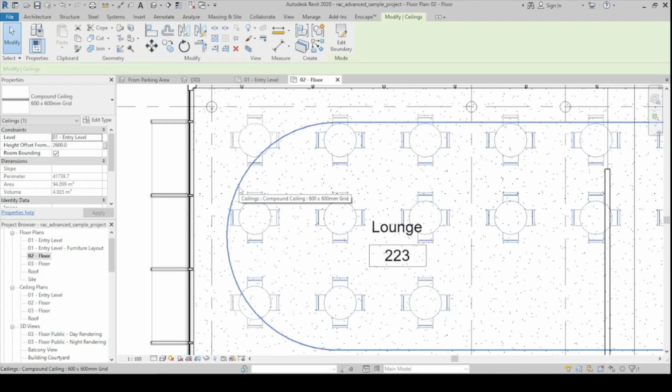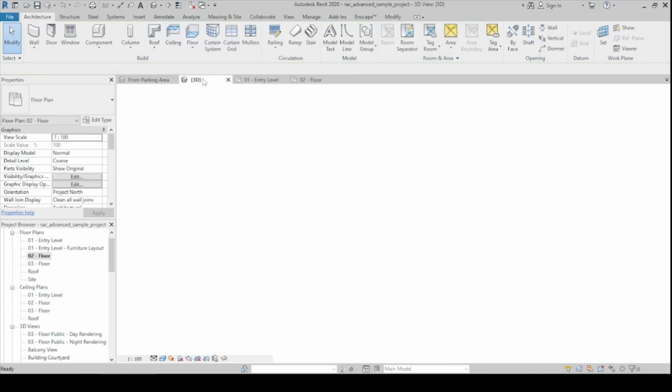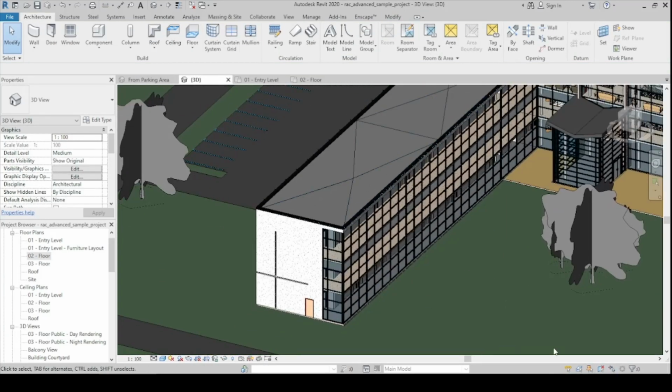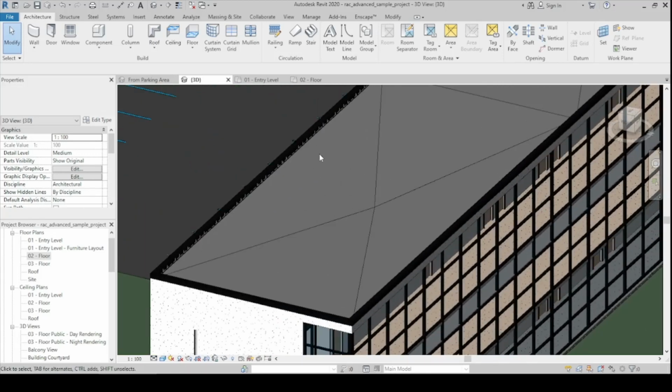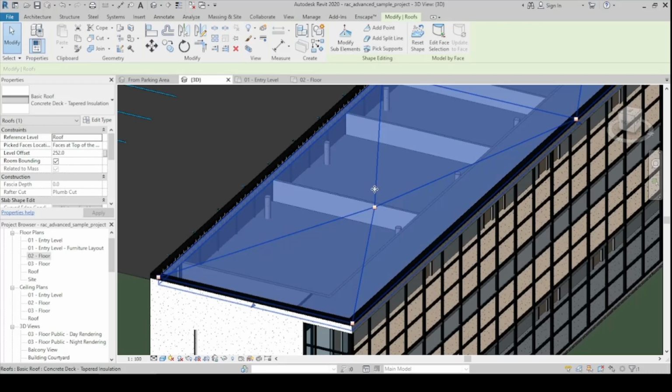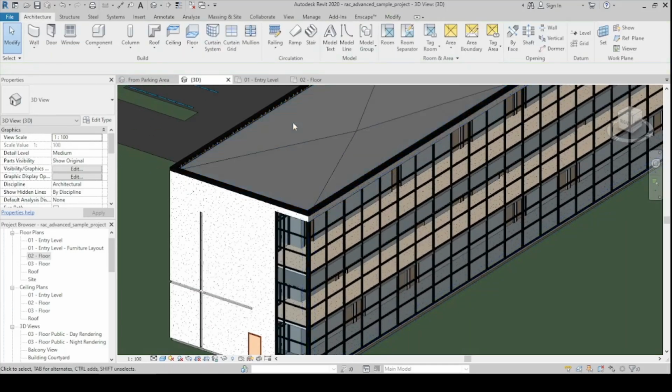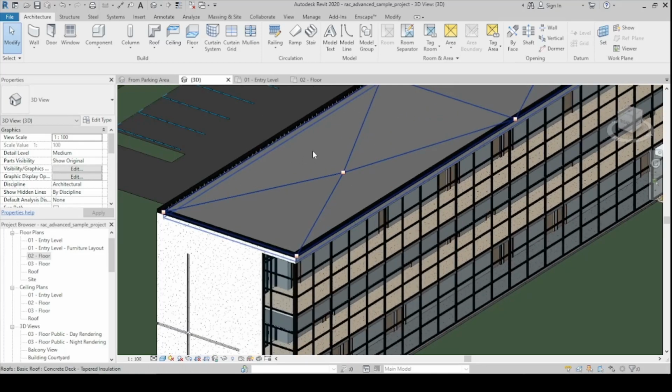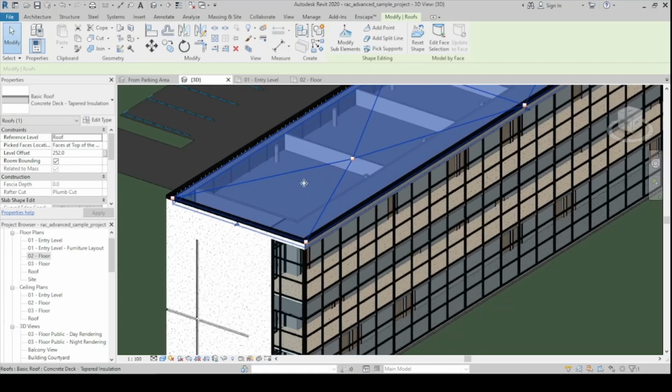only then can we click, no? So, if I go to 3D view, when it is disabled, as long as we are on the face and the cursor does not hit a line, it is not pre-selected and we cannot click. But if it hits the line, as you can see, it is displayed in the status bar. If we click on that, we can select it. Okay? So, that is the difference. If I enable that one, as you can see, even if we do not hit the line, it is still pre-selected and then we can click on that. Okay?